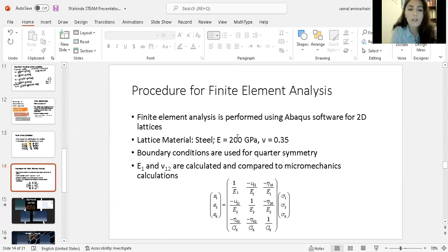We compare the result of our micromechanics calculation to finite element calculation using Abaqus software for 2D. The connecting elements have 0.5 millimeter radius and 1 centimeter length. Only the bending stiffness of the member resists relative rotation at the nodes. Since the members are cylinders, the axial stiffness is dominant. Therefore, the Poisson's ratio obtained is close to a hinged case or a mechanism.